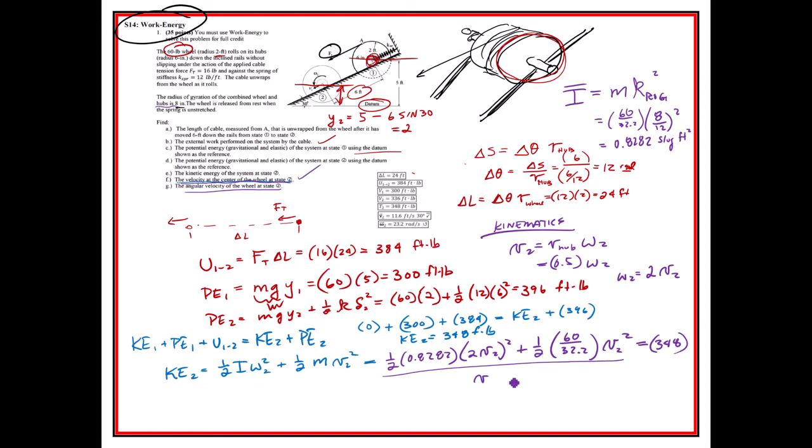And so we get the velocity of 2 is going to be 11.60 feet per second, and that's moving downwards that way. They did ask for velocity, so a correct answer requires an arrow and maybe even the degrees. Really should put that in there.